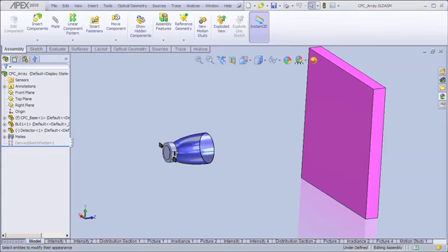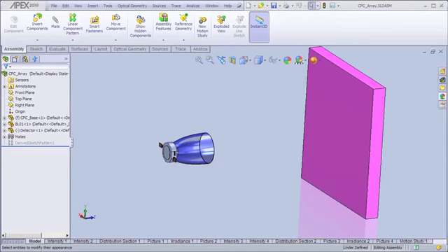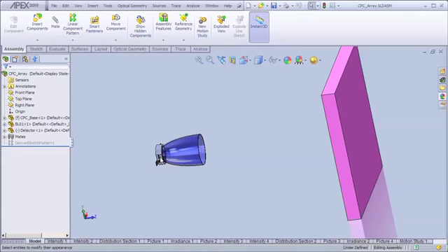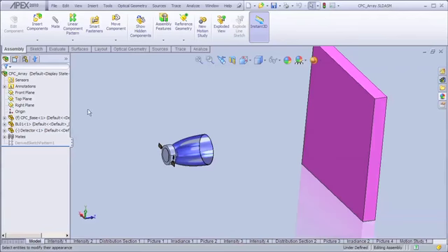In this example, we're going to look at a combination of a compound parabolic concentrator, or CPC, used to minimize the angular distribution of light coming from an LED. In this particular case, we have a commercial LED in our model, and we've got a very accurate representation of this LED, the physical geometry, going into this CPC, and then we're going to take the light distribution from the LED and look at its pattern on this surface at some distance.